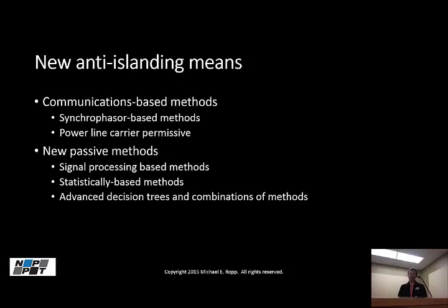The high-frequency system that I was just mentioning a minute ago has a different cost trade-off. The signal generators are much, much smaller, much, much less expensive, a lot easier to install in a sub. But because it's high frequency, there's a propagation trade-off. So they have to have some downstream repeaters and other things to get around transformers and stuff like that. So it's a different market participant there with a different cost trade-off. It's going to be intriguing to see how this works out.